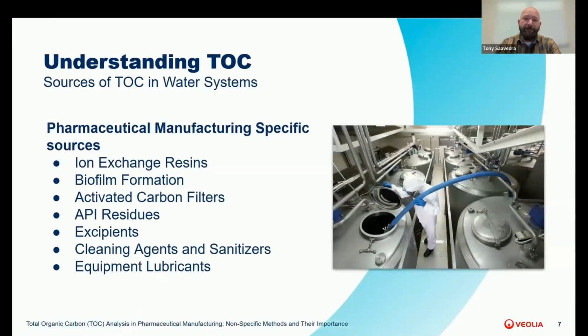Moving into the pharmaceutical industry, there are a few key areas that can contribute to TOC. So ion exchange resins, biofilm formation, and activated carbon filters all contribute to TOC, whether it's through resin degradation or the release of organic byproducts. In addition to those three, APIs, excipients, even cleaning agents and sanitizers and equipment lubricants can also influence the TOC number simply by entering the water system during a manufacturing or cleaning process.